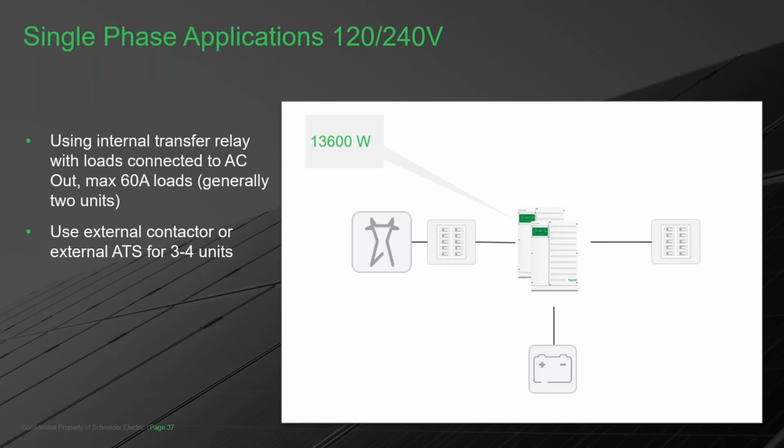As a matter of fact, let's call the DC side the DC bus. So everything on the DC bus, the array, the solar charge controllers, and the batteries are all connected to this new, bigger inverter. So although you see two pieces there, once they're stacked as master and slave, they're going to behave as a single 13.6K system with the overload capability of 17K for 30 minutes.